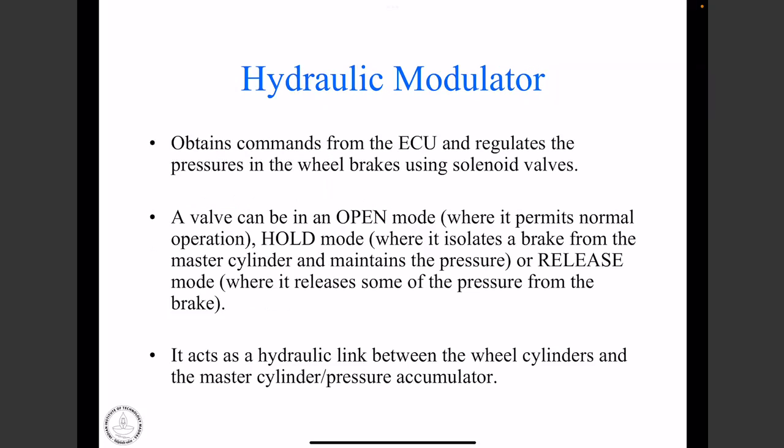So I think one of us raised this point, right? When ABS acts, we seem to get some tactile feedback at the brake pedal, as if there are some vibrations. What is going to happen? If you look at a typical ABS modulator, for the time being, let me consider a hydraulic modulator, which is used in a hydraulic brake system of a car.